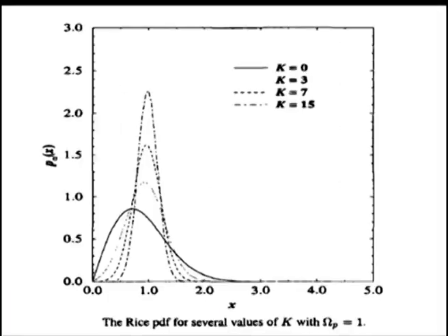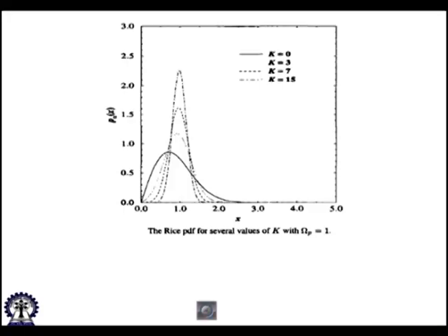So, with this what we can see is that the amplitude coefficients which are received are random, although you are sending a constant amplitude signal, a continuous wave transmission, and the signal is complex Gaussian distributed. The envelope is Rayleigh distributed when there is equal distribution of power from all directions. We will see more details, and when there is a specular component, instead of Rayleigh distribution, there is Rician distribution. For Rayleigh distribution, the squared envelope, which indicates the signal power, is exponentially distributed, whereas for the Rician case it is more cumbersome. For the Rician case, if you put k equals 0, you end up in a Rayleigh